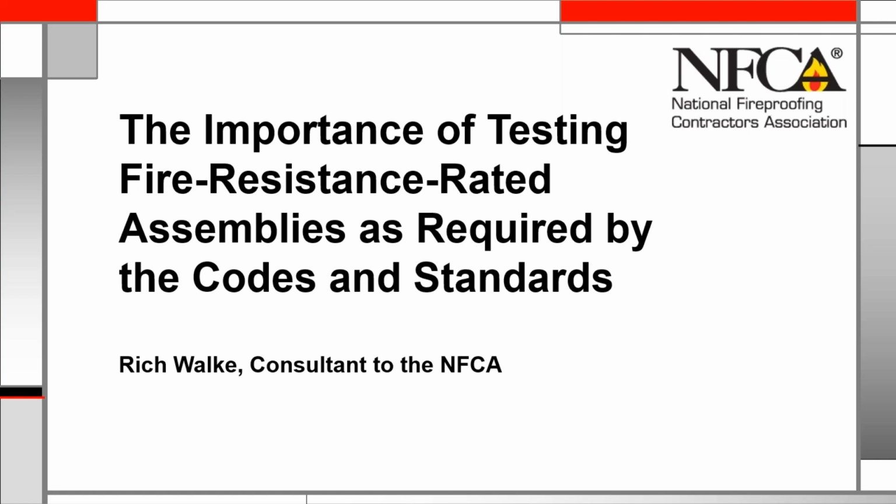These terms are not defined by the codes and standards, but do have widely agreed upon definitions in the industry. So when I say full-scale testing, I'm referring to testing of an assembly meeting the minimum size requirements of the two standards used to establish fire resistance ratings, ASTM E119 and UL 263. Small-scale testing is testing of an assembly which is smaller than that minimum size as required by the standard. For a number of reasons which we'll discuss shortly, testing assemblies which are smaller in size than required by the two standards is a less critical evaluation.